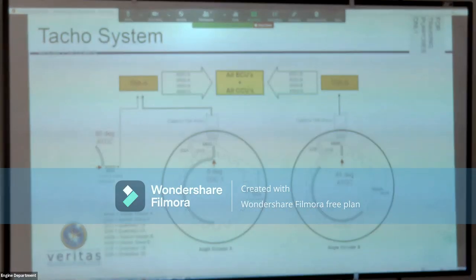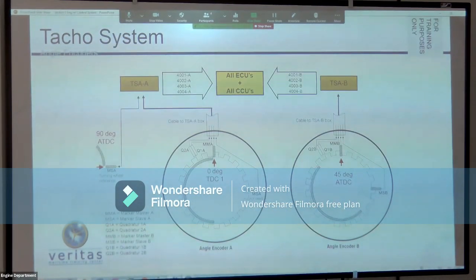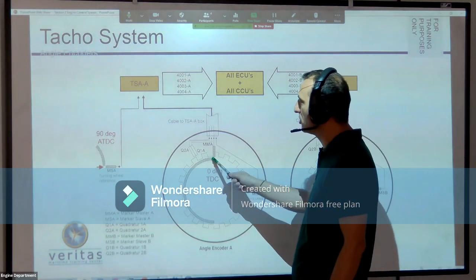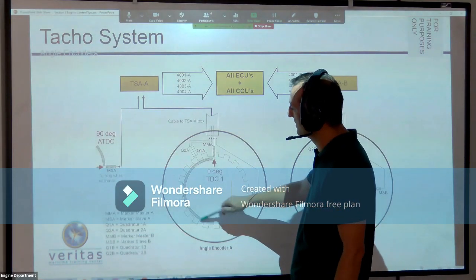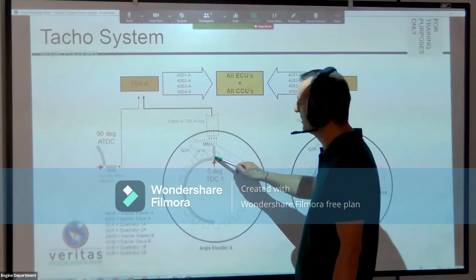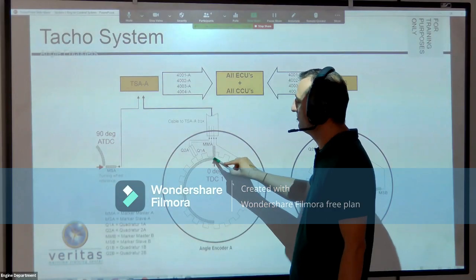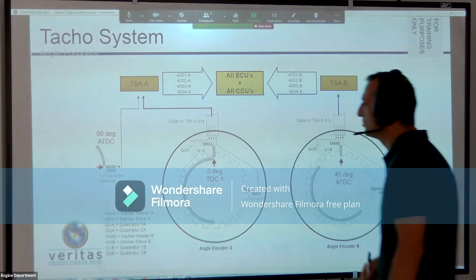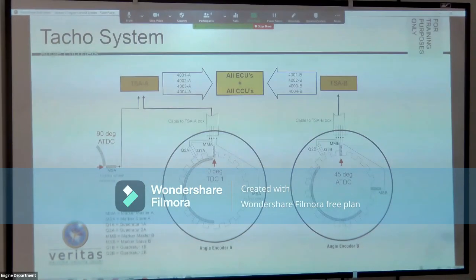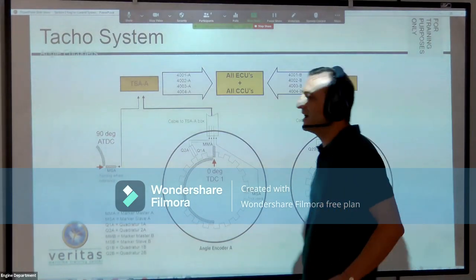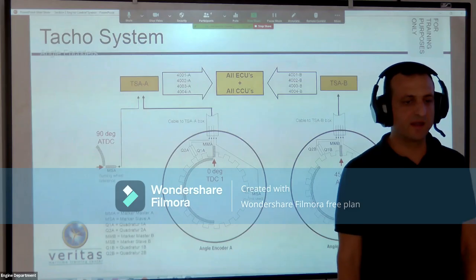So how many times is the marker sensor activated per one engine revolution? One time, yes? It is activated by this semicircular ring. So now it's on, it remains on until it gets to this position and then it will be off. When this ring reaches another revolution, this area, it will be on again. So the marker sensor is activated once per revolution.